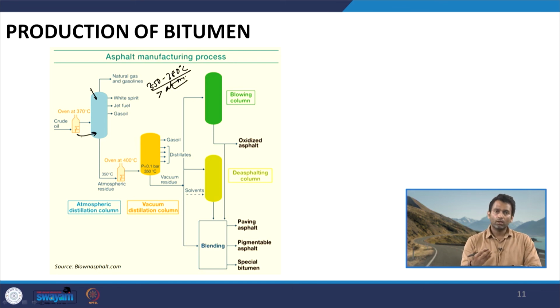Once the crude oil is introduced in heated form, the vapors will start rising in the column, and subsequently lose heat. When each fraction in the crude oil reaches that particular punctured tray where the temperature is just below its boiling point, that fraction will condense into liquid and can be collected.